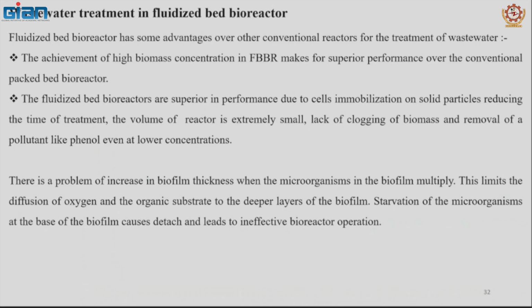This limits the diffusion of oxygen to the core area. Limit the diffusion of oxygen and the organic substrate to the deeper layers of the biofilm. Starvation of microorganisms at the base of the biofilm causes detachment and leads to ineffective bioreactor operation.